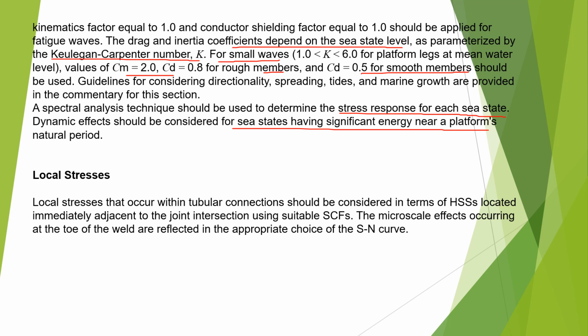And moreover, directionality, spreading, tides, marine growth. These also should be considered. Guidelines are available. The important thing is that kinematics factor of 1 and conductor shielding factor equal to 1 should be applied for the fatigue waves. So kinematics factor and shielding factor, both are 1.0.